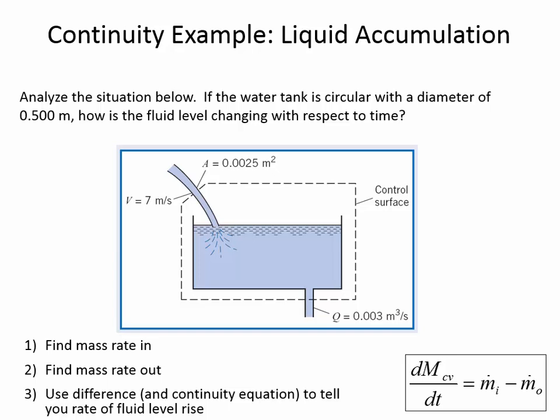And over time, what you saw is that the flow in was the same as the jet out plus the overflow. The water level eventually stopped rising. At first it was rising before any water was going out. At first it was rising very quickly, but then as soon as the water started going out through the jet orifice, it started slowing down a little bit. And then the jet flow was increasing as the liquid level went up. And so the liquid level is rising even more slowly because the flow out through this orifice increased. But then finally it came into equilibrium when the water level got to the overflow there.